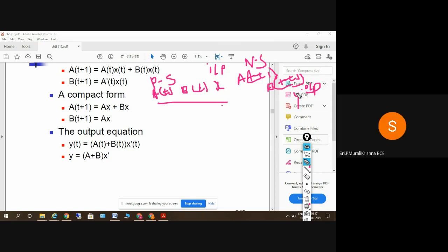Okay, so this is the state table, and when we get the equations, what we have to do here is substitute those values. Present states and inputs will give the next state. A combination of present states and inputs gives three variables here. The variables range from 000 to 111, and all these a of t, b of t, and x values are substituted into the a of t plus 1, b of t plus 1, and y equations. From this we'll get the values of a of t plus 1, b of t plus 1, and y. Clear? So that is what we have to do right now.